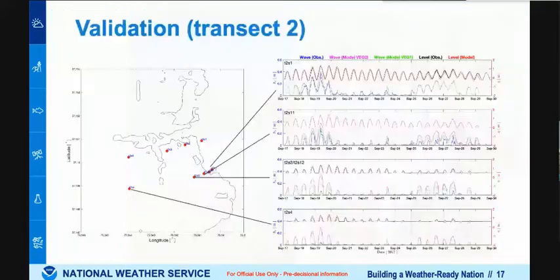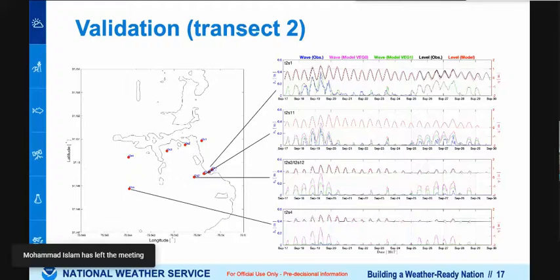So here, transect 2, as you can see, for validation of the ADCIRC and WaveWatch 3 models, we had a grid with 5 meter resolution in Magothy Bay, but it was covering the entire East Coast, and I think the size of the grid was about 700K nodes, but the concentration was in Magothy Bay with 5 meter resolution, which is a wetland, and we needed to resolve the channels in that area. The gauges were located from wet to overland, from top to bottom in this plot.